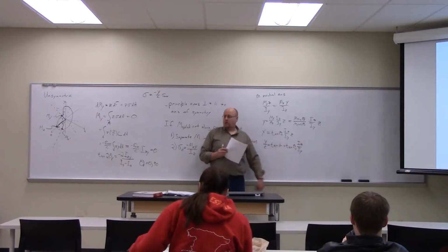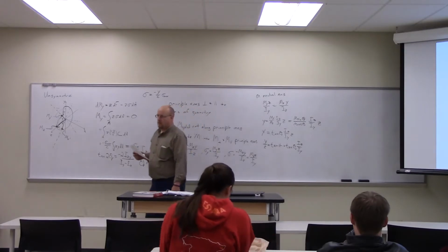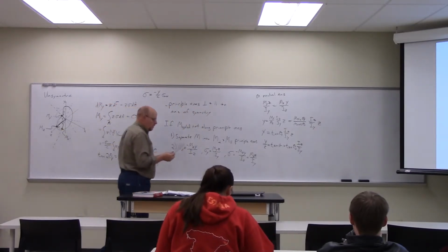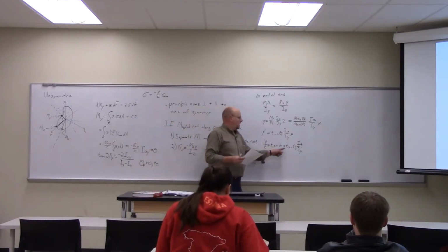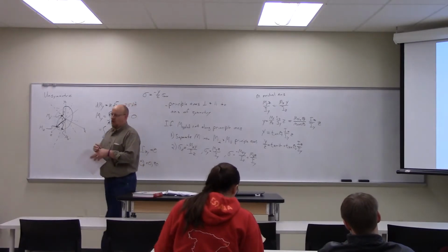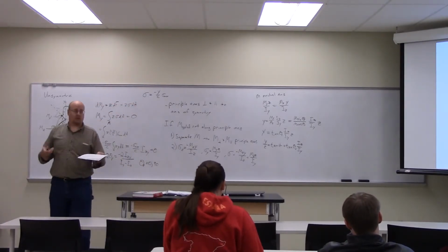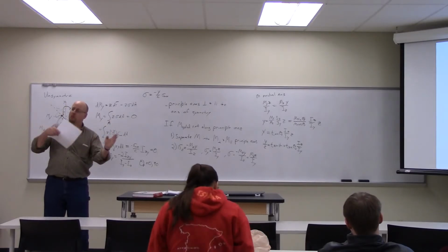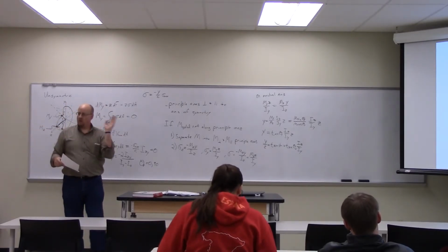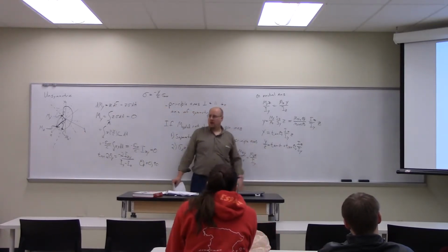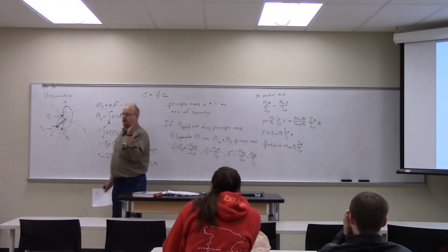And if Iz and Iy are equal, then theta and alpha are the same. So in a case like a square cross-section, where the moment of inertia about both principal axes is the same, then the neutral axis will be aligned with the principal axis.